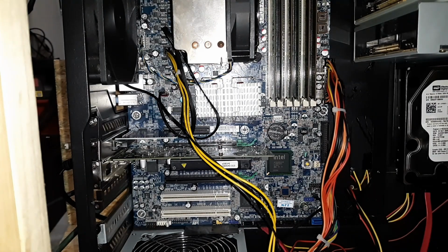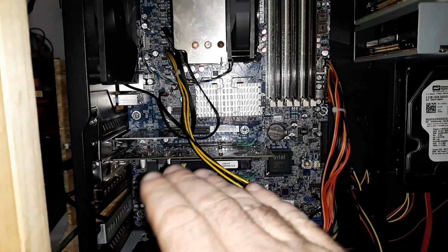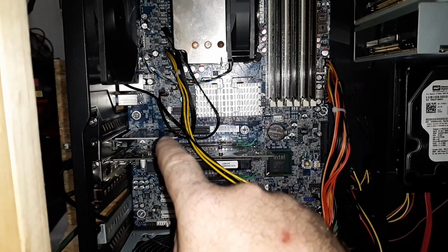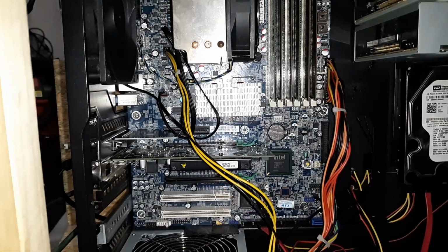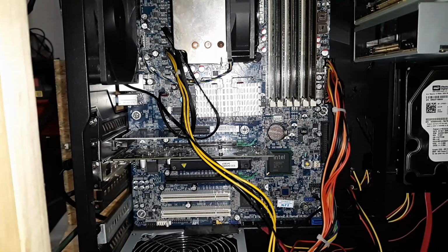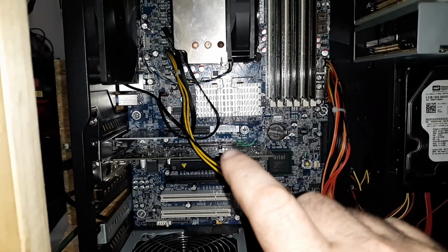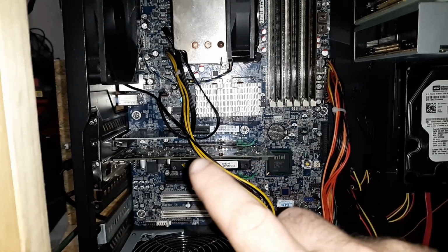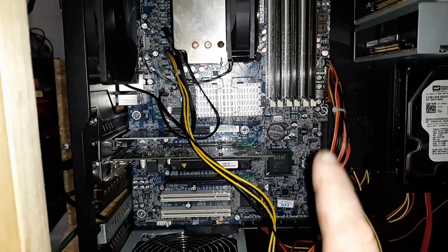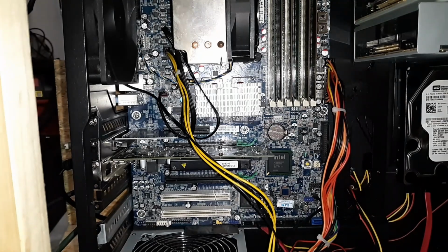So I hope that explains some of it, because I saw a lot of people having trouble with Mach3 and Mach4 trying to run a parallel port. That won't work. And I spent hours trying to figure out what was going on. And I physically pulled it out, tested the pins, and I realized I'm only getting 3 volts up at the board. And that board requires a minimum, I think, of 5 volts to even run correctly.